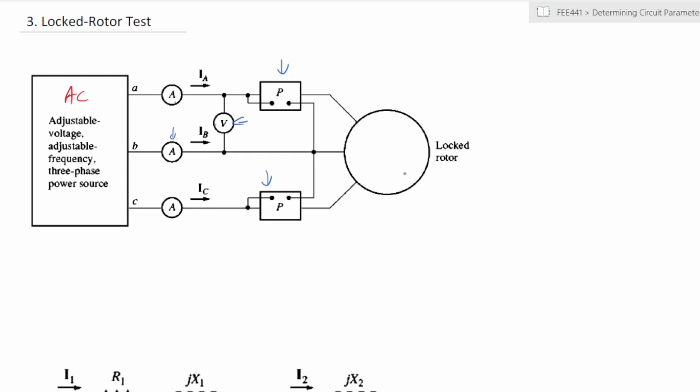So you just find that the rotor keeps drawing more and more current, which could be damaging to the motor itself, right? In practical situations, if the motor locks up, that is why your motor burns out. The windings of the motor burn out because it attempts to draw more and more current to be converted into a power that can overcome the locked rotor, right?